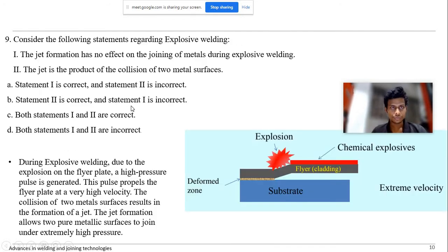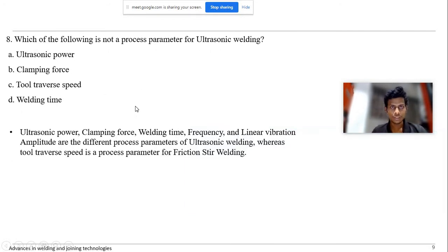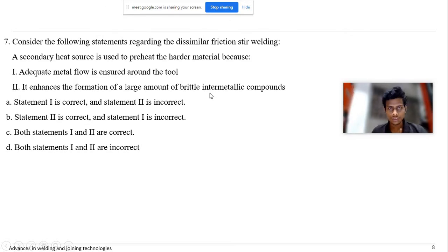And also, I forgot to tell one more point. Sorry. As it started, in solid state welding we generally go to avoid brittle intermetallic compounds, right? So next class maybe I'll give some examples. If you do aluminum and steel welding, what kind of intermetallic compounds will be formed, which are adverse to the welding, which we need to avoid.